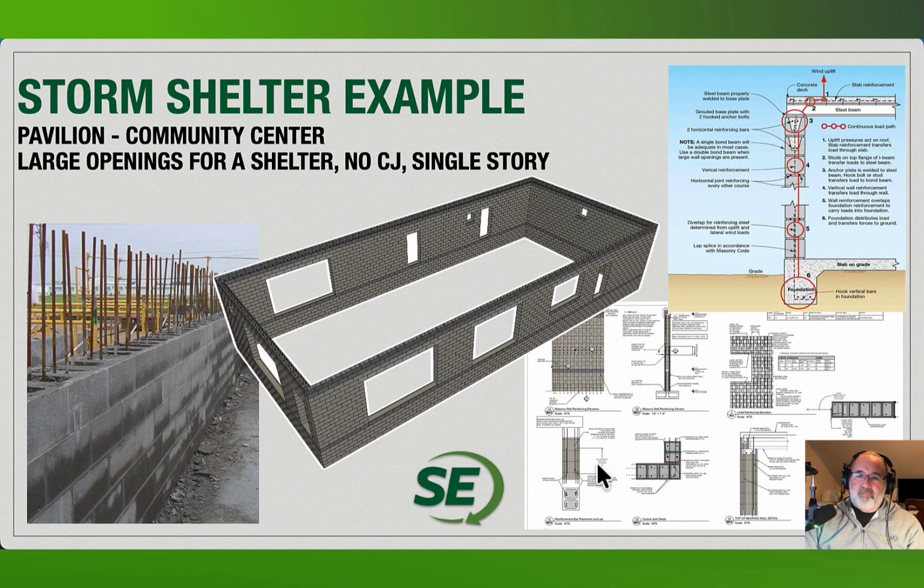And then another example that we've recently completed is a community shelter pavilion. You can see that it looks a little bit non-standard for a shelter, with relatively large openings, and those openings had some very significant heavy shutter doors that were designed for them, and then connecting those doors to all the different elements around and reinforcing. So even though this is a single story, this is also a 12-inch design because of the overall sizes of the openings. But we laid it out, detailed all the different reinforcement, and had that continuous load path all the way down to the foundation for this storm shelter design.